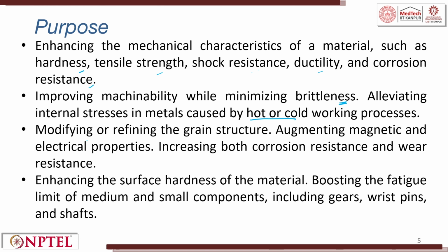It also helps in modifying or refining the grain structure. If you want to make a smaller grain structure, you can do it by heat treatment. Augmenting the magnetic and the electric properties, and increasing both the corrosion resistance and wear resistance are possible by heat treatment. It also enhances the surface hardness of material, boosting the fatigue limits of medium and small components including gears, wrist pins and shafts.